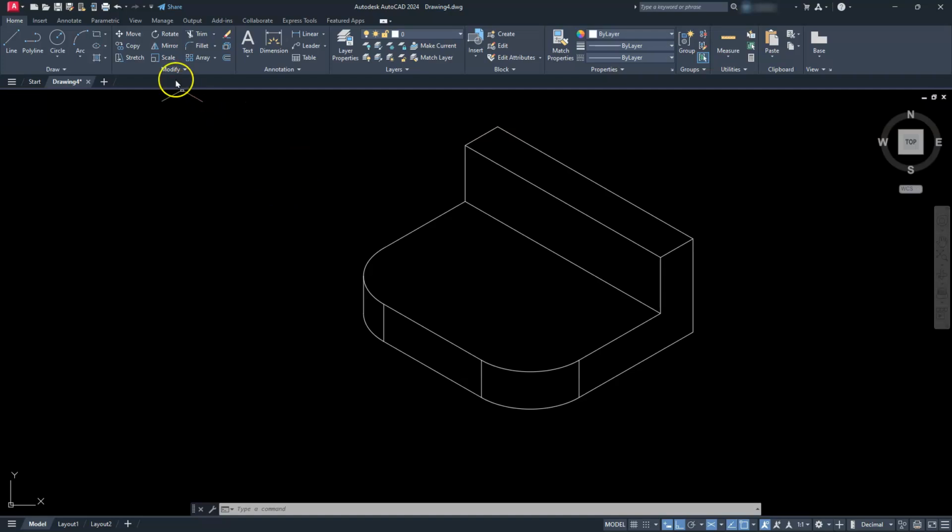So let's go back to the lengthen command like we did before. So I'll go to lengthen. Then I'll choose delta. -20 because I want to subtract from these lines. Enter. And then I'm just going to select these lines here. And we have 3 more to select. Or 4 more, I should say. Alright. So now we have our lines created.